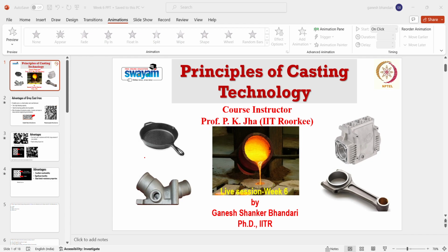In quenching, you take out that material at a temperature of 800 or 900 degrees Celsius, and you put that material in cold water, which will be at around 5 or 10 degrees Celsius, or you can talk about frozen water also, subcritical temperature water, at around -20 or -10 degrees Celsius.